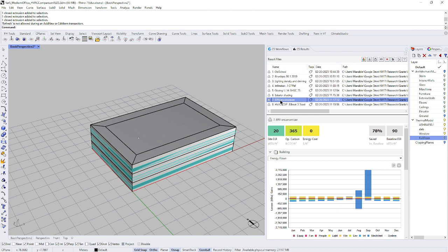What an ERV, or an HRV, an energy recovery ventilator, does is allow us to exchange the heat and, in an ERV's case, some relative humidity with our indoor air as we're dumping it outside to get fresh air coming in. So we can save a lot of energy that way, because we're getting fresh air, but we're not losing energy.